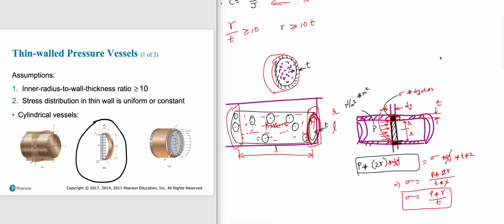This is the stress. So how does this stress act? This stress acts out, right? So this opposes this pressure acting in the tank. So this pressure or this stress developed is not only on this highlighted, we just took a thin small strip, but it is not just on that solid black color region, but it is all along this section that you made a cut. And we can make all semicircular cuts.